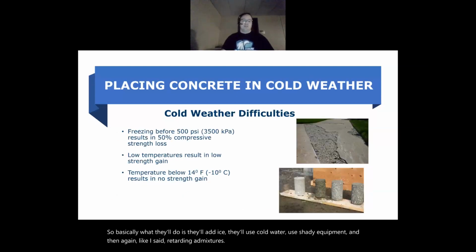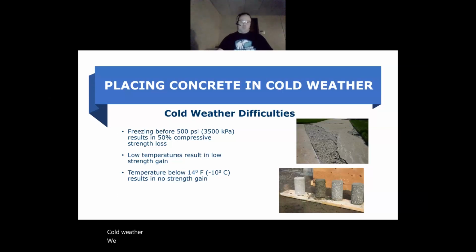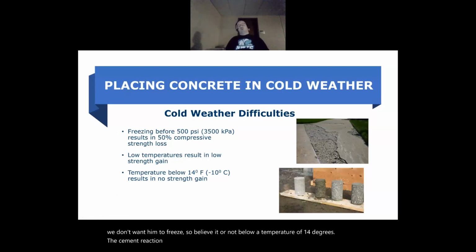Cold weather, we don't want it to freeze. Believe it or not, below a temperature of 14 degrees, the cement reaction stops. Once it stops, it will restart, but it will not be at 100%. So you've basically ruined the reaction, and the concrete quality is not there anymore.